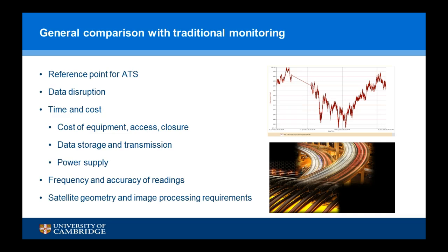In terms of accuracy of readings, it wasn't shown in this particular study, but another study that we did looked at setting up actual corner reflectors at a fixed site and imposing movements. And the scale of accuracy for these types of movements is in the millimeter scale. Literature says that it can be sub-millimeter in very carefully controlled conditions. But in the kinds of things we were looking at, we were seeing in the 2 to 5 millimeter accuracy range for these types of experiments.